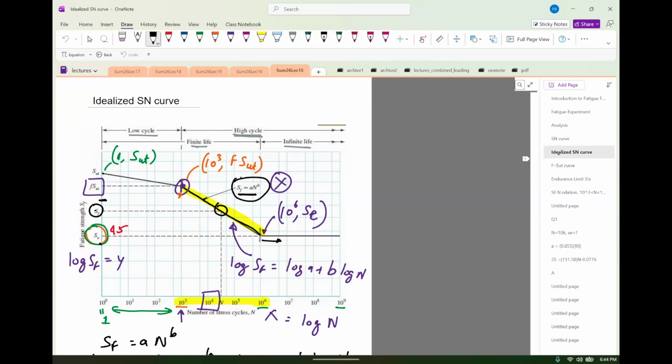I would say that this is going to fail very soon, and so there's no real point of finding the exact cycle. Having something fail at 1 cycle or 10 cycles or 100 cycles is nothing, right? Because if something spins fast, it'll probably complete 100 cycles in no time. So really, you can just say it's less than 1000 and you stop there. You don't really compute that it is 944. It doesn't really matter. Because the cycles to failure are so few, you just say it's going to fail within 1000 cycles and you don't bother.